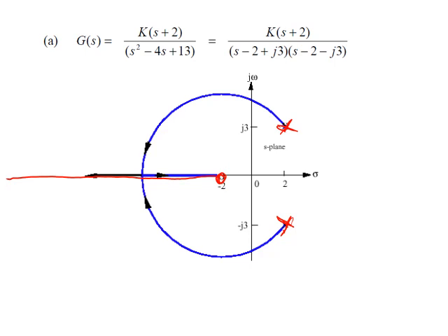What are the other rules? We have to keep the symmetry. The drawing is supposed to be symmetrical. So if it's symmetrical, we are going to take this point until here, and it's going to continue its way toward infinity. So it's going to go in this direction and this direction. And for the other one here, it is going to go this way, this way, this way, then it's going to go to the pole, to the zero, sorry. So that's how we satisfy all the rules of root locus.